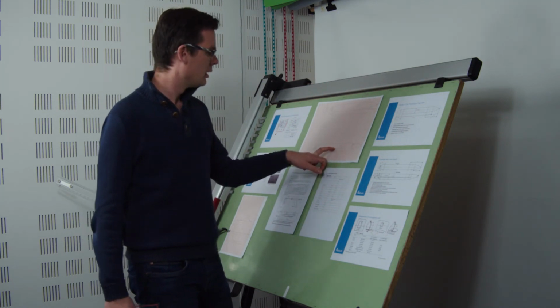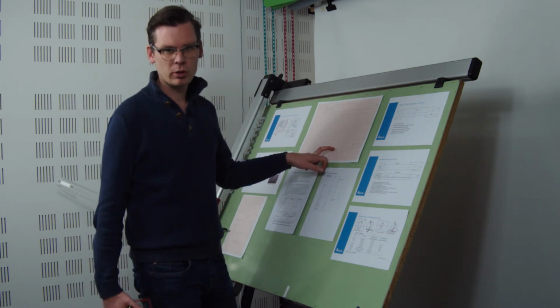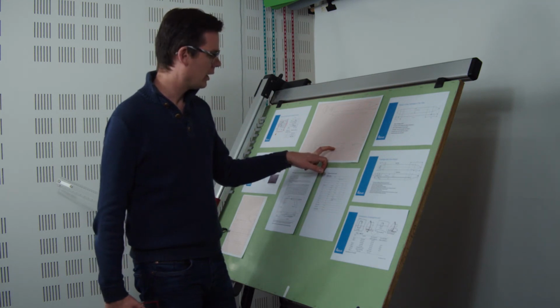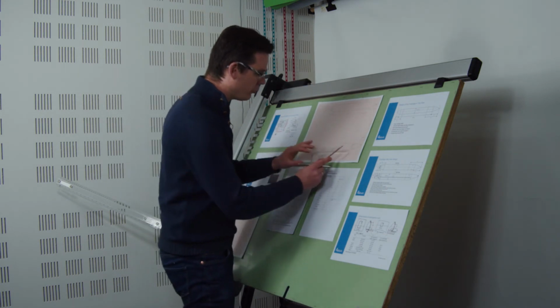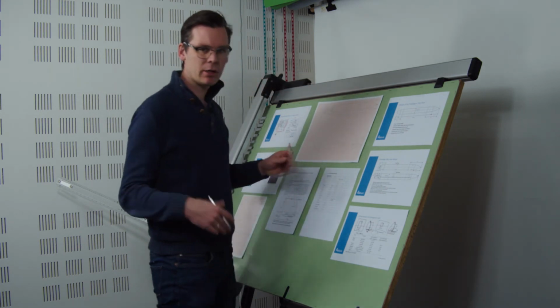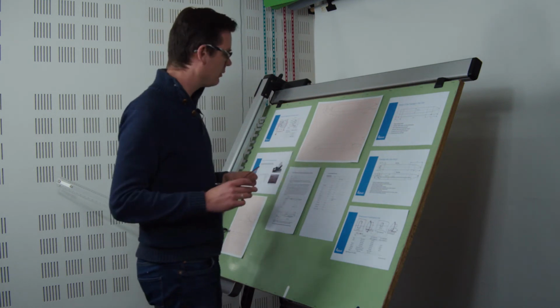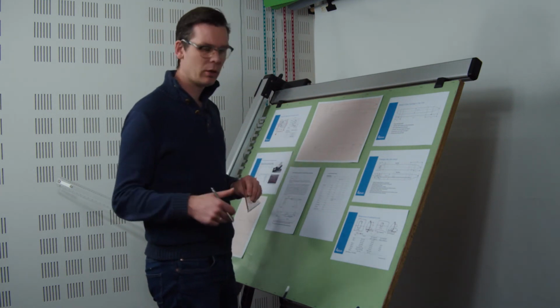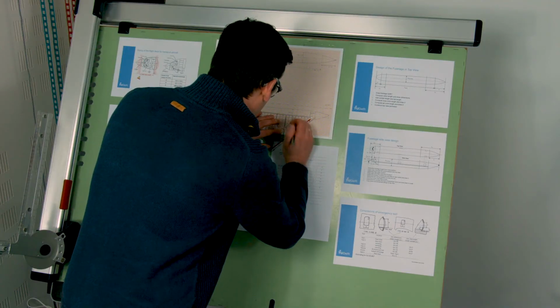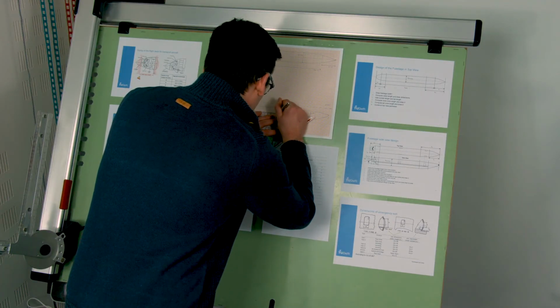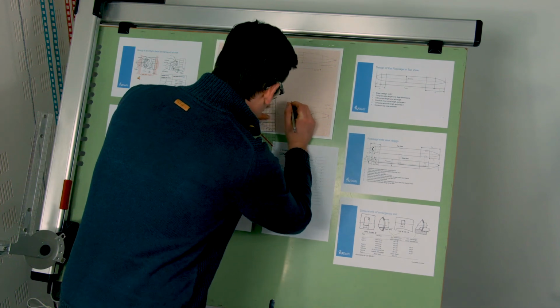We haven't even decided if this is going to be a high wing or a low wing airplane, but for now I'm penciling in a type 3 exit at a height of 40 centimeters, and later on, if we decide to do things in a little bit different way, we might have to rethink that. But that's the iterative approach that I'm taking. So 50 centimeters wide, somewhere in the middle over the wing, and 90 centimeters tall.